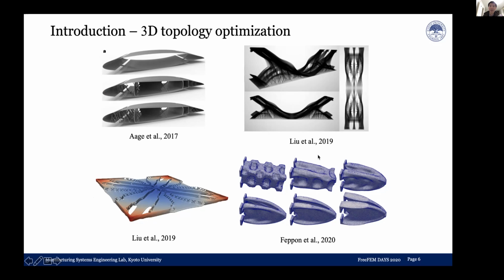But here we wanted to mention that their method uses the Hamilton-Jacobi equation for updating the level set field. And we must set many holes for the predefined structures, and the shape will vary based on the shape derivative, meaning that new holes cannot be generated during the iterations.